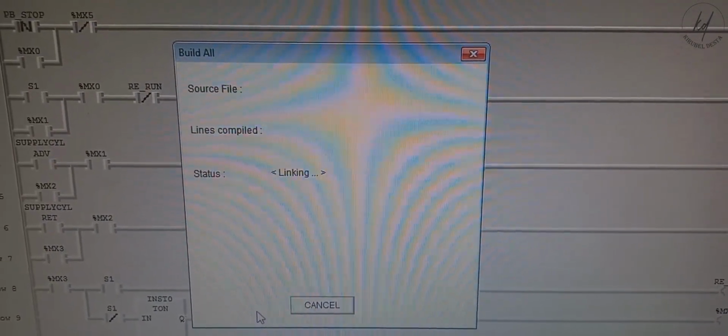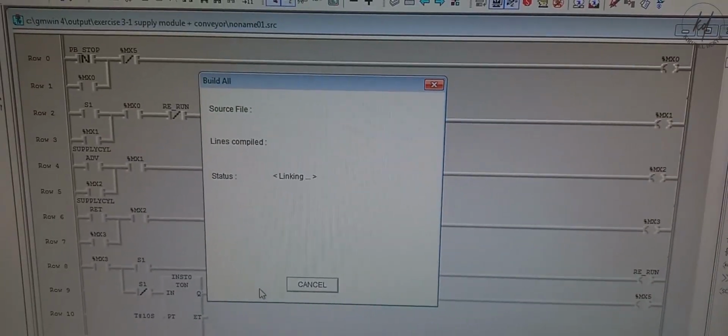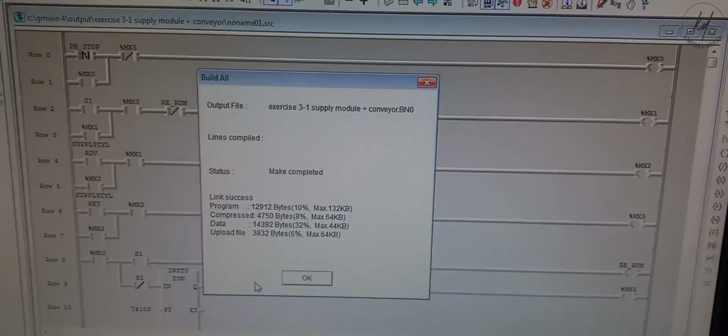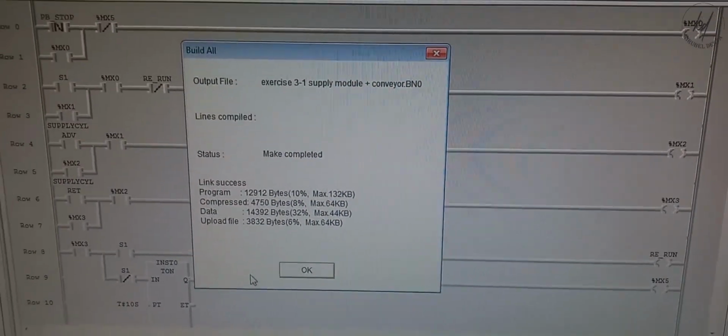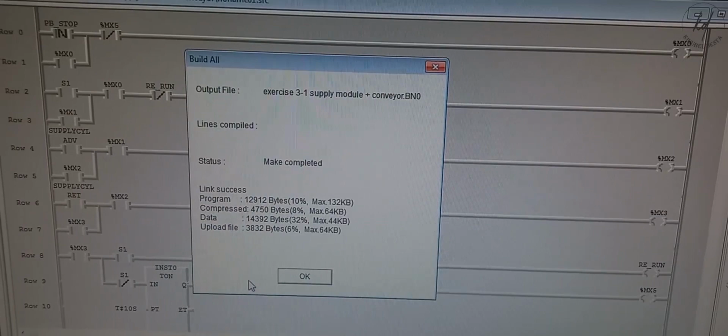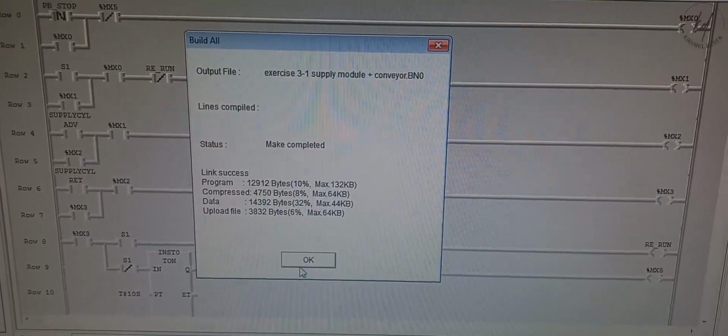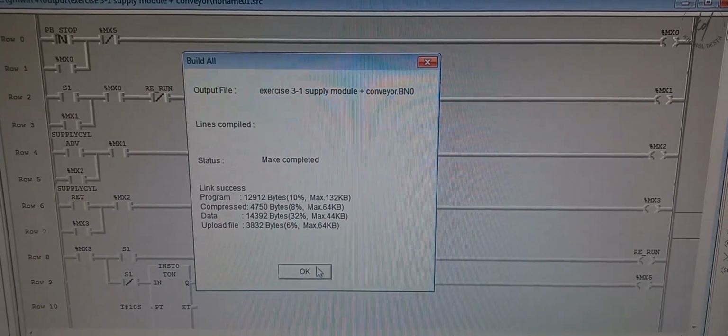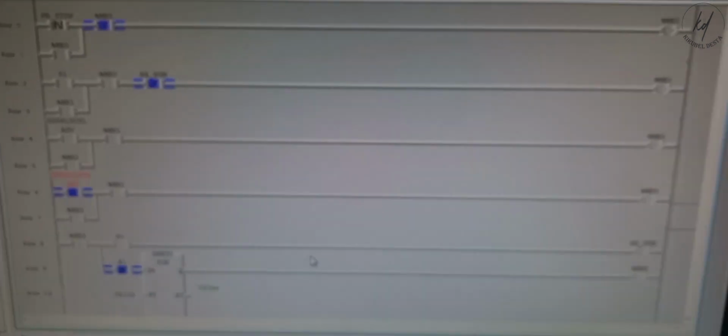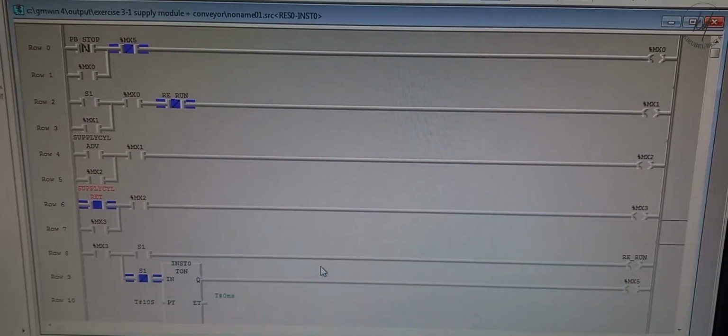In row 2, the MX1 coil tag can be energized if the sensor detects an object. It senses, MX1 is activated and self-holds, and now its effect goes to row 15, the solenoid valve advancement. As a result, in row 4 the MX2 coil is energized and self-holds. Due to this, its effect goes to row 15 and deactivates the solenoid valve, that means it returns back to